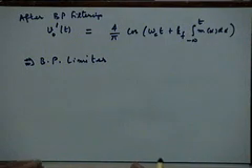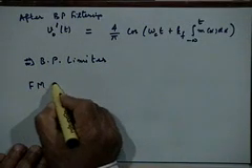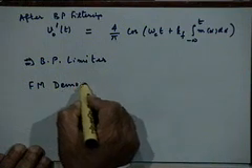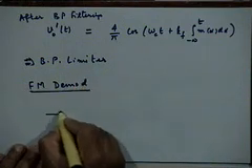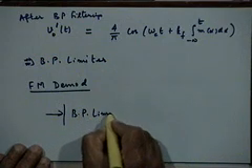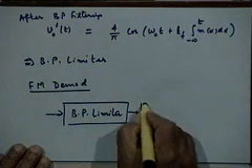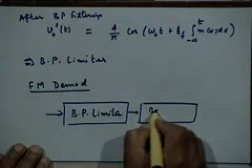So, I hope now with this discussion it is clear how a band pass limiter works, and it should also be clear that an overall FM demodulator must contain both these devices, right. It must first contain a band pass limiter, right, followed by preferably a balanced discriminator.